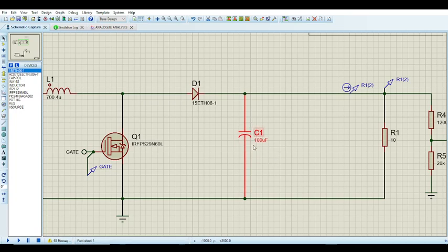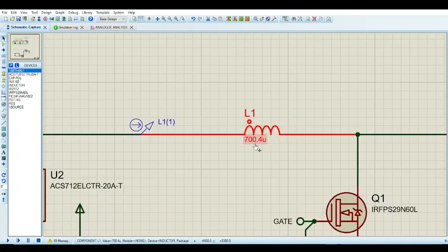And you don't want them to exceed 100 microfarads, especially for such a high frequency like 100 kilohertz. 100 kilohertz is not super high, but it's a reasonably high frequency where you could get away with using conservative values for an inductor and a capacitor. Obviously here it's 700 micro, it's not so conservative, but you are running it in CCM, so it's better that it's a little bit larger than required than lower.